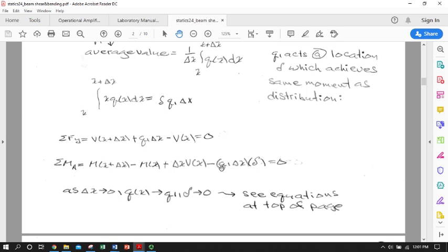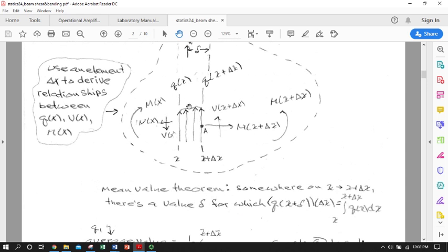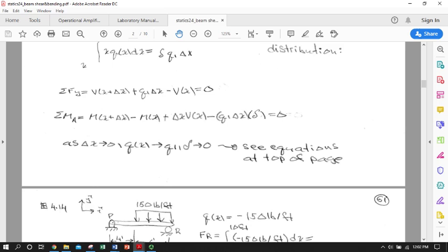And if we do a units check, you can remember that Q sub 1 should be in something like newtons per meter, delta x should be in meters, and then this delta function will also, being positioned, be in meters. So this has got the correct units. And it's got a negative sign because it's heading up and would produce effectively a clockwise moment.